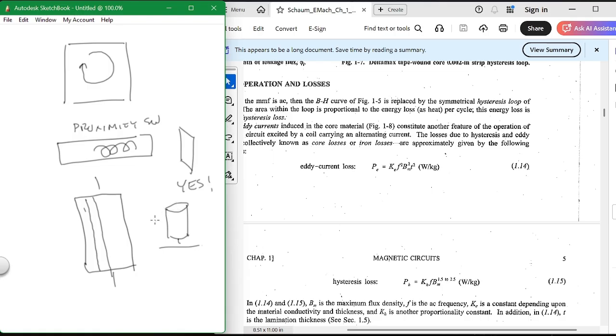So even without any laminates at all, you can still get it to spin. It's pretty weak, really wimpy, but it does spin, okay? Even without the laminates, you can still get eddy currents onto this, and they're constantly turning, so they're pushing it one way or the other. Now if you take three-phase to a motor and turn any two wires around, you reverse the direction of the motor, don't you?